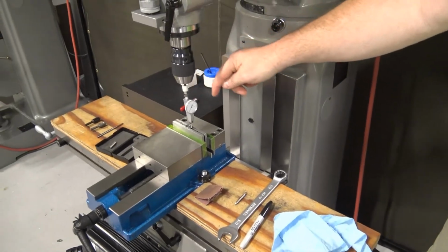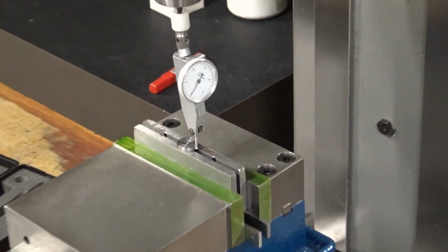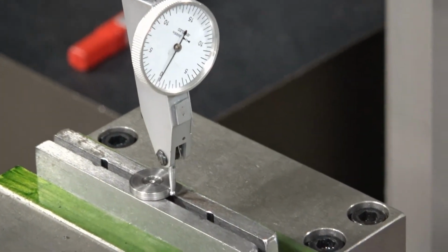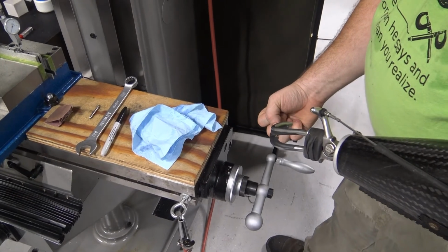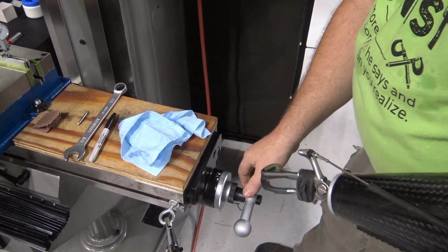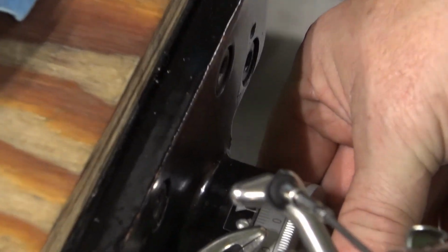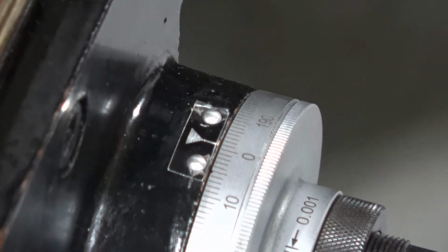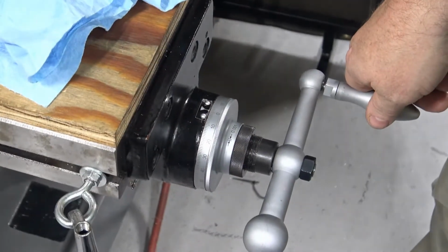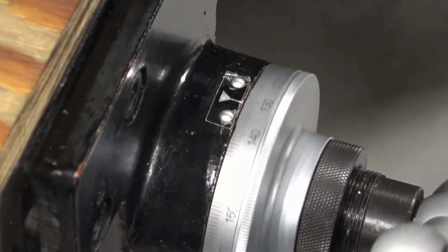So I've checked 180 or 360 degrees around, and I'm reading 0 with my dial indicator. Set my dial to 0. Last movement that I made was clockwise. Notice that I'm right at 0, off a little bit. Dial that in, and now we're going to move 188 thousandths, which is not quite one full revolution.